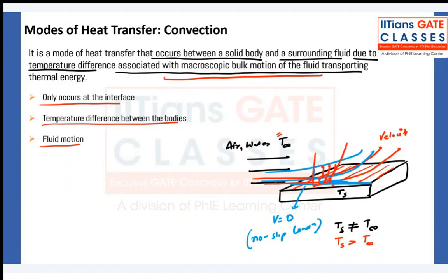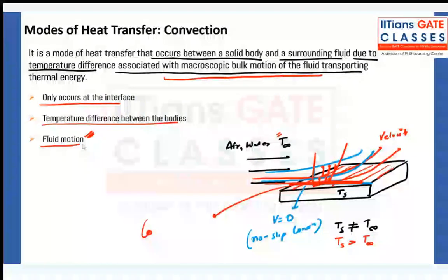So at the surface, what is happening? Conduction is happening, because I have told you that for convection, there must be fluid motion. But at the surface, because of the no slip condition, fluid velocity is zero. So between solid and fluid, conduction is happening. So, is that clear? You were asking about different phases, so different phases we have, but conduction is happening.